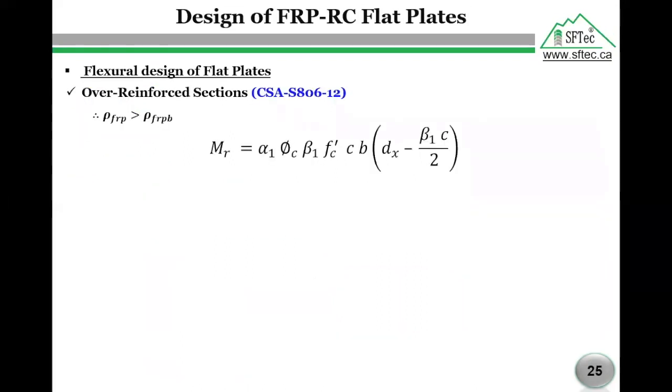The second step in the flexural design is to estimate the straining actions on the floor, such as the negative and positive moments and shear forces. All of us are excellent and can do that using any finite element program like SAP or SAFE. Now we will consider that we have the values of the factored negative and positive moments. So the next step, we need to estimate the amount of FRP bar.